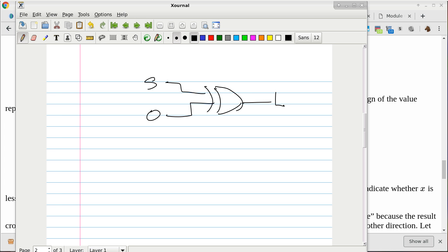You can put this into the carry look ahead design. The concept of an adder and a subtractor, they don't really care about whether it's signed or not. They are the same for signed versus unsigned. The only time you need to know whether it's signed or not is when you need to make a decision based on, is that less than that? Then you need to use these flags.